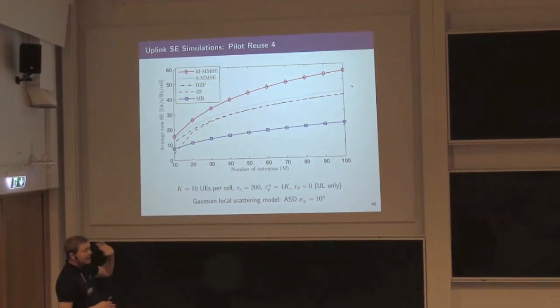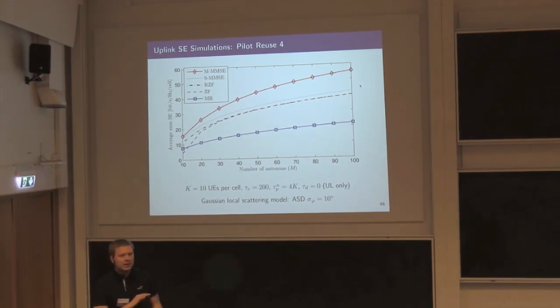But for any scheme here, even if there would be no interference or anything like that, as you add more antennas, in the best case, the SINR will grow linearly with the number of antennas. And then you put a log 2 on top of that. So in the best case, it will grow as the logarithm of the number of antennas. And it has this kind of shape so far. So it's not saturating, it keeps growing. It could do that. And the hint is that some curves here will saturate, some will not. But we'll come back to that.